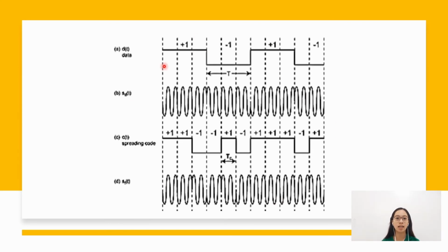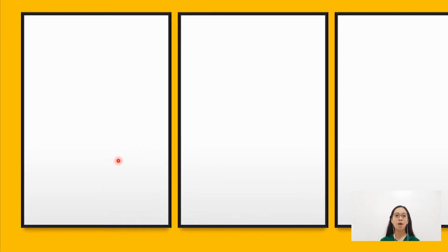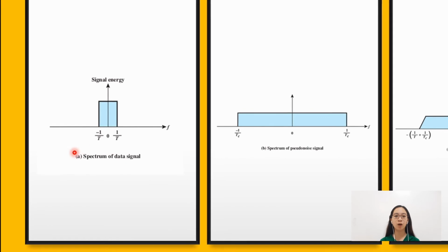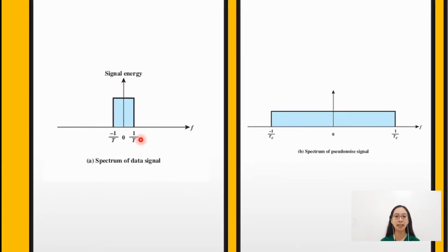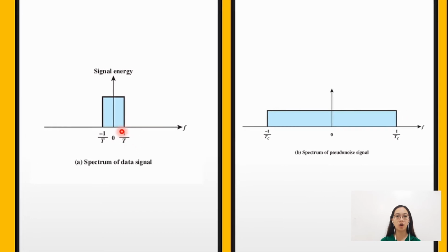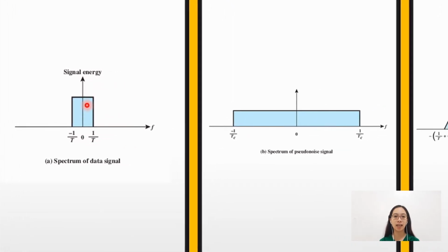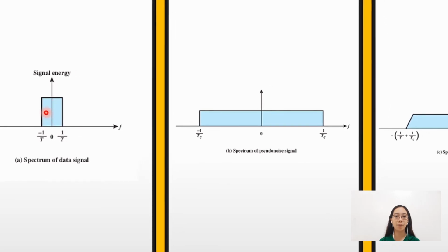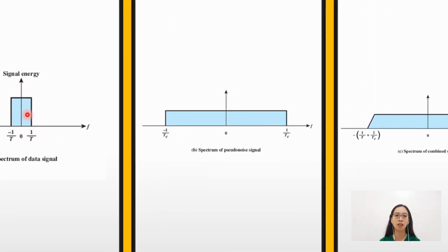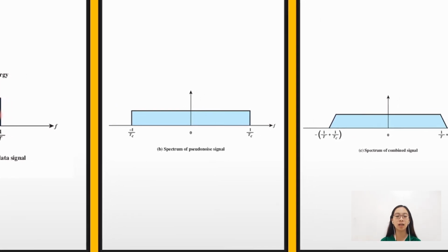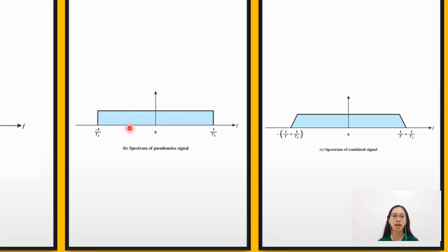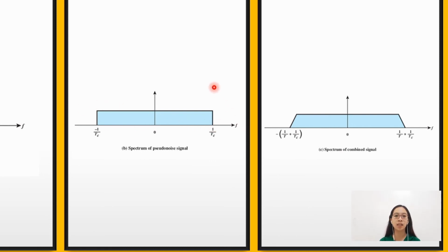The second method is the discussed method using the BPSK scheme as shown in the figure. Approximate spectrum. The information signal has a bit width of T, which is equivalent to a data rate of 1 over T. In this case, the spectrum of the signal, depending on the encoding technique, is roughly 2 over T. Similarly, the spectrum of the PN signal is 2 over T. The amount of spreading that is achieved is a direct result of the data rate of the PN stream.